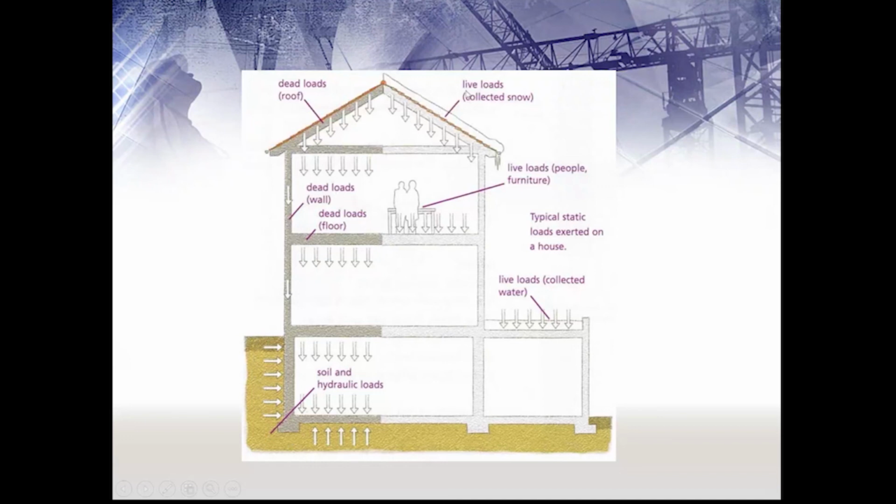For the snow, most of the time, if the snow is heavy, it will stack on the roof for a moment until it melts and falls down. But during that time, when the snow is stuck on the roof, it brings an additional load. So during the design, if you are in an area that has winter and there is a probability of having snow, we will consider the snow as a live load.